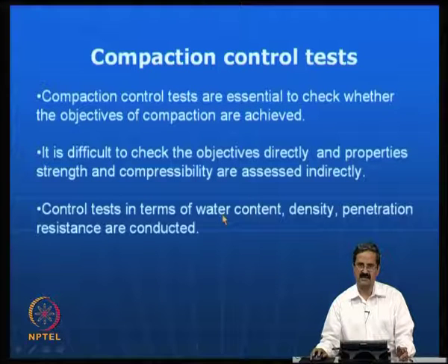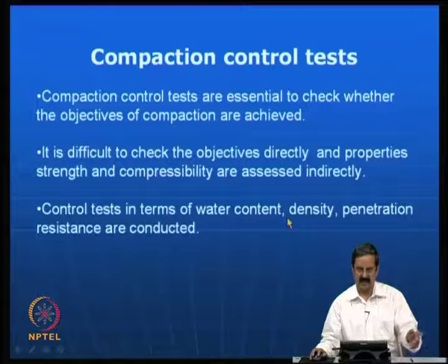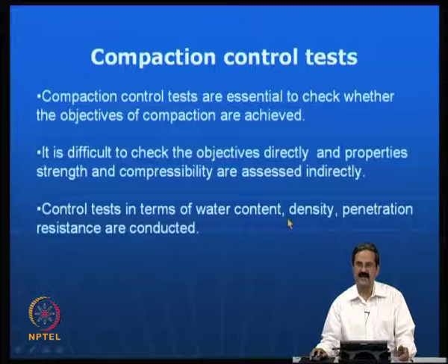And if the water content is not really in the same range, then you need to really worry about it. So, density is the same thing. Say for example, we know that the compaction curve in some cases is something like parabolic or some sort of curve, which means that any small change in the water content or the compactive effort could lead to a lot of change in density.